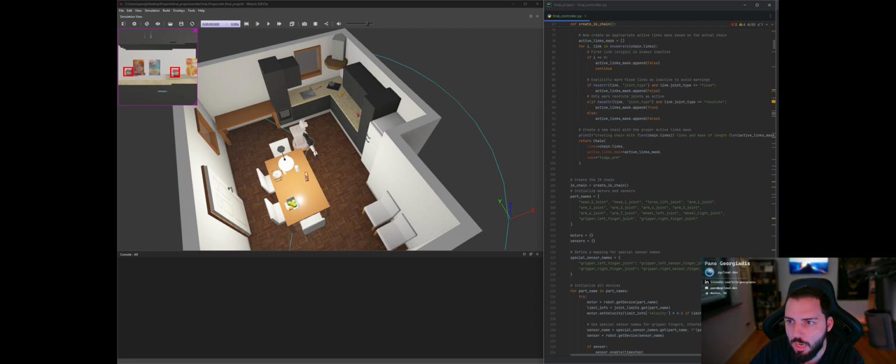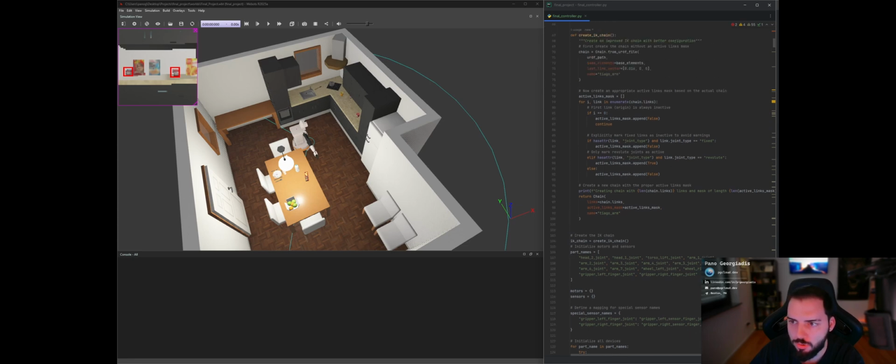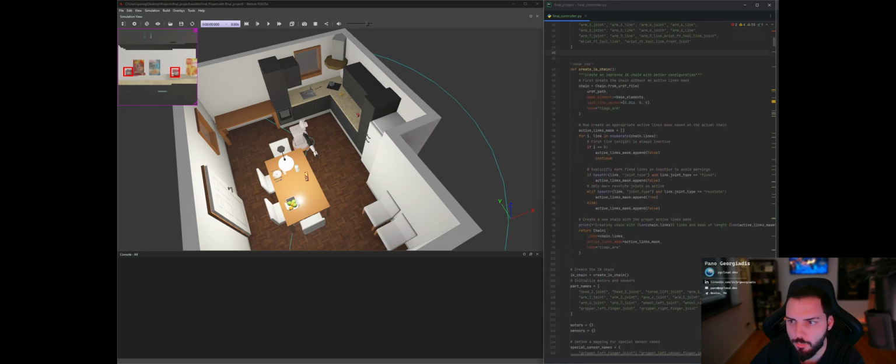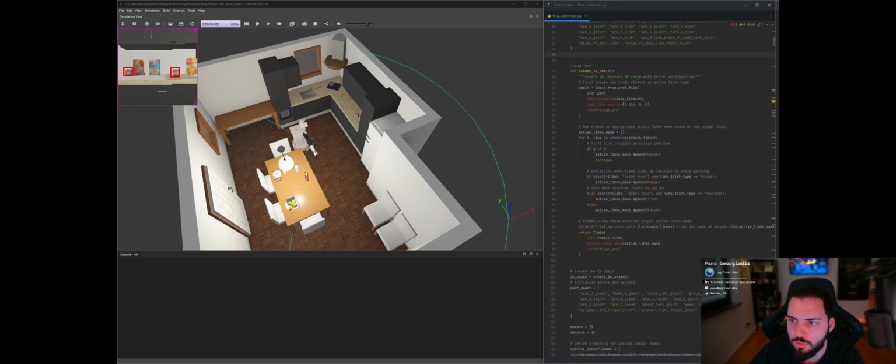And then the IK solver integrates joint limit enforcement to prevent physical constraint violations, initial configuration optimization for stability, which you'll see in the constant of the prepare arm for movement, and then the orientation constraints for appropriate end effector alignment, as well as numerical optimization with configurable iterations and precision.